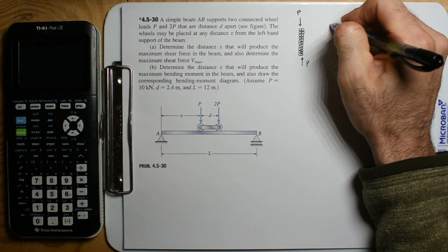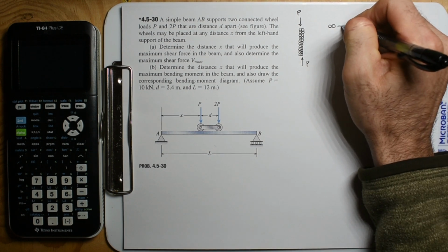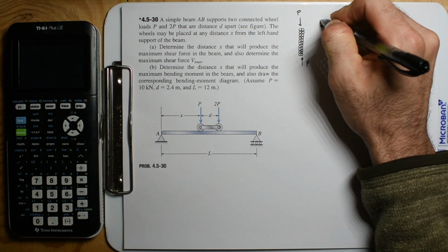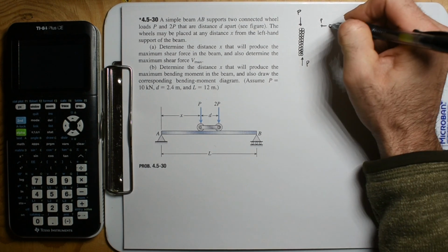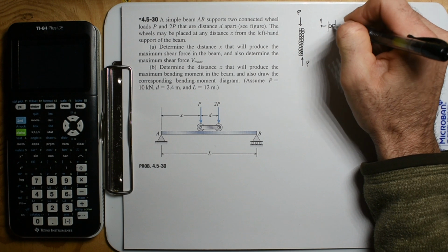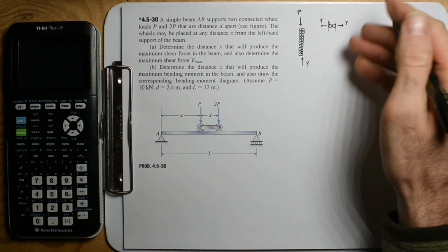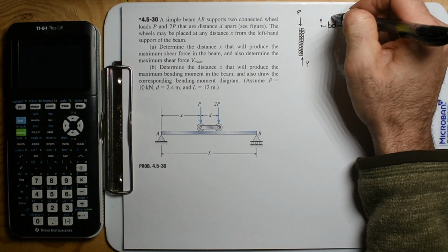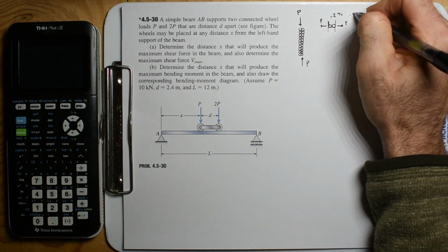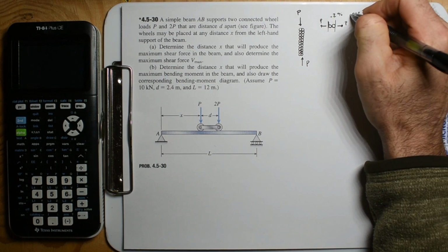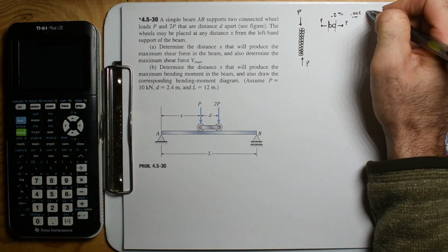And we know that if we have 2 molecules this way in material mechanics, where if we pull on them, all we really have to do, if it's steel, and this is like the length of that molecule, is increase the length by 0.2%. So that's a 0.002. That's going to be the fraction of the entire length.